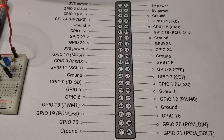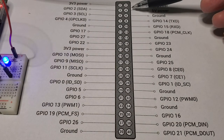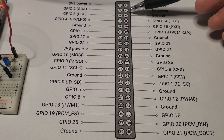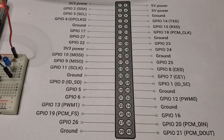So quickly going through the header here. At the top, we've got a 3.3 volt power rail. We've got a couple of 5 volt power rails here, and there are 3 or 4 ground pins as well. There's one here, there's one here. Well, actually, there's more than 3 or 4. As you can see, all the other pins on here are GPIO pins, and you can use any one of them for general purpose input output. And then some of them have special purposes.